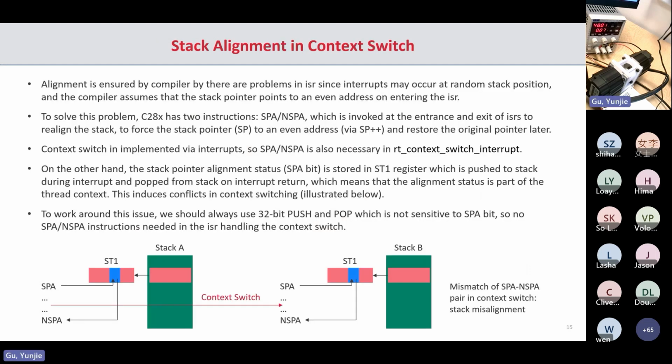And this one is a little more difficult, and that is because the memory and the stack are not aligned in the same way as other standard devices. It's either 16-bit or 32-bit, and the 32-bit variables can only be put at even addresses.